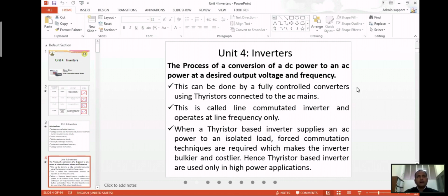Now, as I have been talking about, our hydropower systems really suffer in isolation mode. When they were commissioning Mangdechhu, they were trying to run our systems in isolation mode. They were not successful, even in the Mangdechhu case, because when there is a change or variation in the load, there is a failure in the grid and the whole grid collapses.